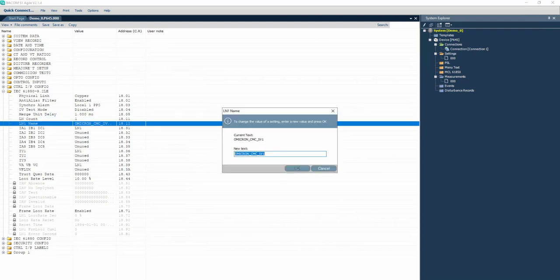This is for the SVID. So this is configured in the CMC. As you can see here, Omicron_CMC_SampleValue1. That's where we put the name for the sample value ID. This is how it's going to distinguish different sources for sample values, by this sample value ID.